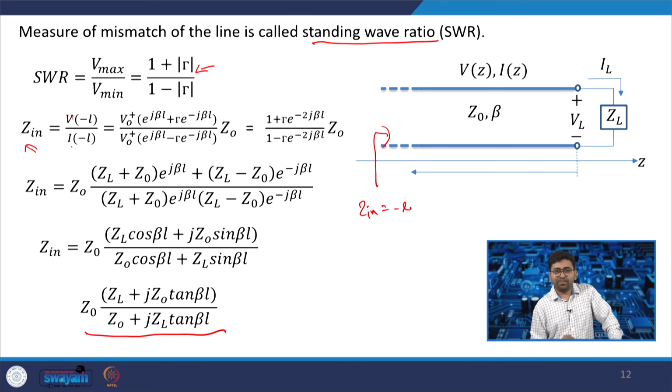This is a very important equation because you can easily get the input impedance Zin of a transmission line when a certain load ZL is connected, and all microwave or RF circuit designers use this equation to find the input impedance at one side of the transmission line.